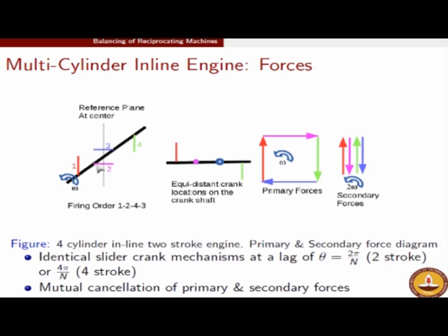Then the next question comes as firing order. The next question of firing order is answered in this fashion: as a convention we take the first cylinder to be firing first, which is always at the top dead center. Now if 2 is at this orientation, then the next cylinder to fire, once the shaft rotates by omega, this 2 will come at the top, right?